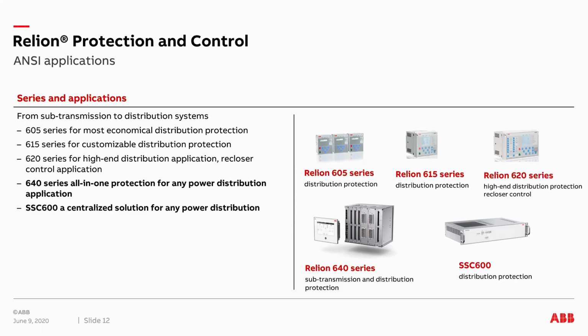To mention a few things about the 615 series: this is one of the popular ABB series being used globally. For that matter, any product under Relion has a common naming structure: RE stands for relay, and the third letter tells you the application. For example, REF means it's a feeder protection relay, F for feeder.